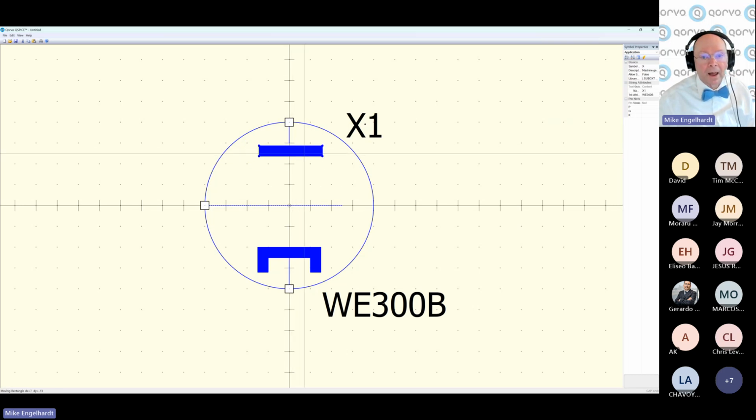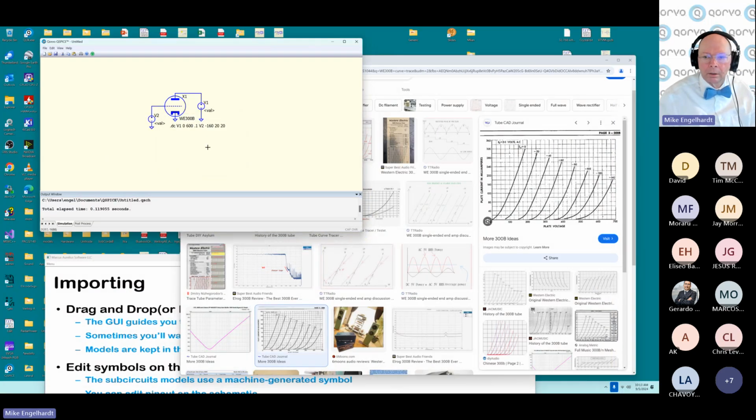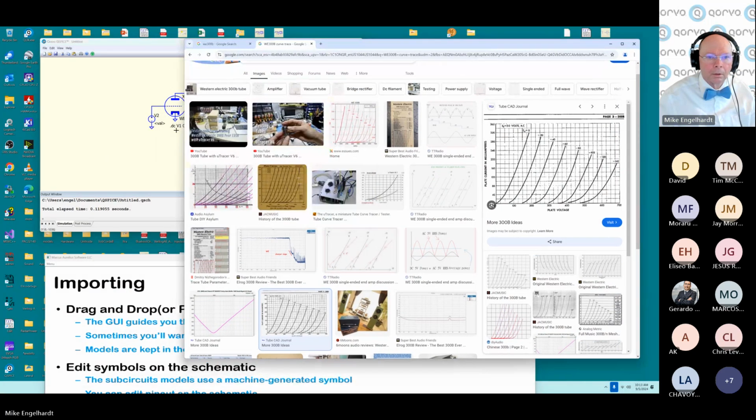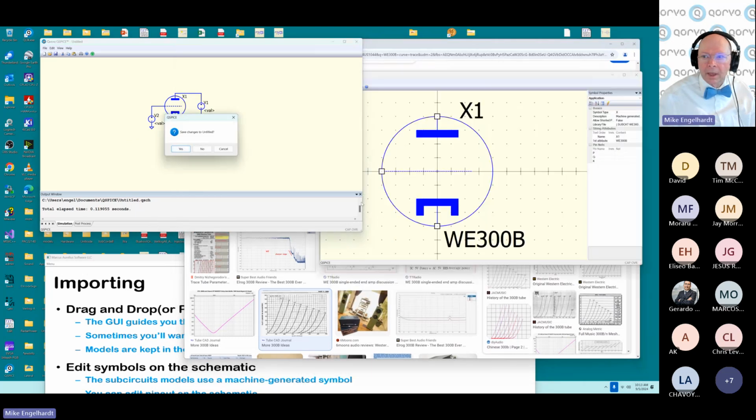Now I'm at the final, 1/100th of a grid. So that's where you get it. It's Shift, Control, and Alt. The more of those keys you press down, the closer you get to the smallest grid you can use. So you don't need to remember which one does what. So that's including third-party models.